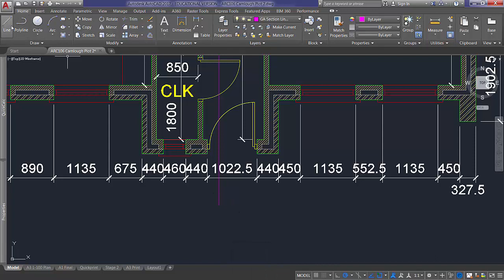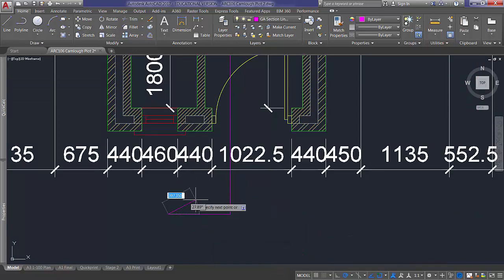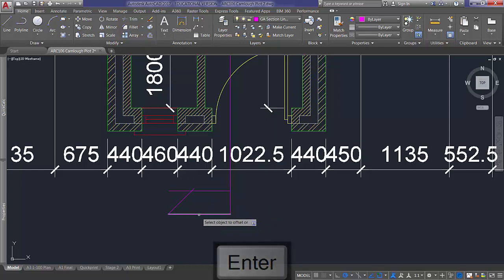and we can indicate the direction of the section as well. That could be done potentially using a leader from the annotate tab, but I'm just going to draw a simple arrow here. So let's draw a line 800, and let's get an angle of 45 degrees like so. Okay, maybe just let's offset that by 300 just to see exactly where that is.